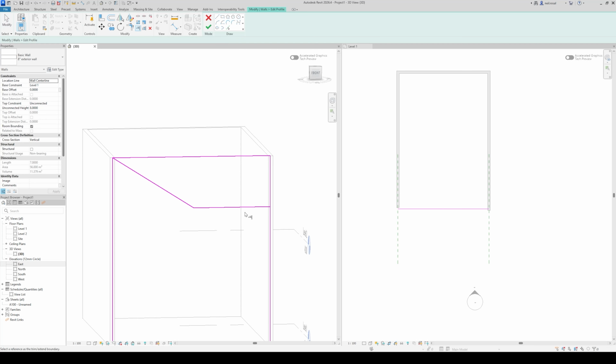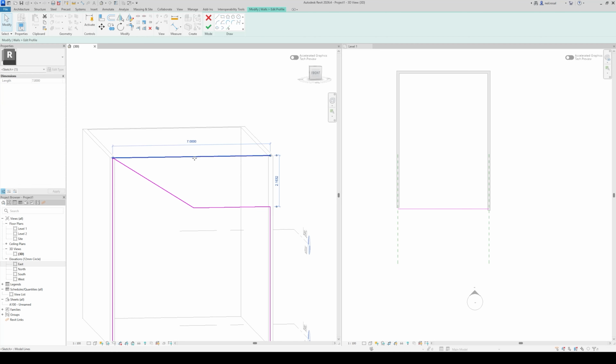In trimming in Revit, you want to keep the line you want to maintain in your model. So as in Rhino, you want to set your boundaries. I want to set this as my boundary because I want to take this away. So I keep the line over there. I want to keep this side of the wall, and then I just want to delete this line over here.